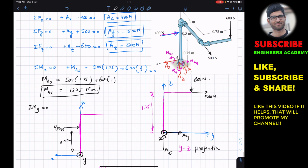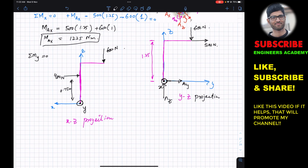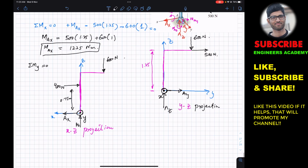Similarly, this 500 Newton force is along the y-axis, so it will not be visible in this free body diagram, and this 600 Newton force is acting in the negative z, so it will be visible somewhere here. This is that 600 Newton, and here the AX reaction will be visible and the AZ reaction will be visible, and the AY reaction is out of the screen, so that will not be visible.